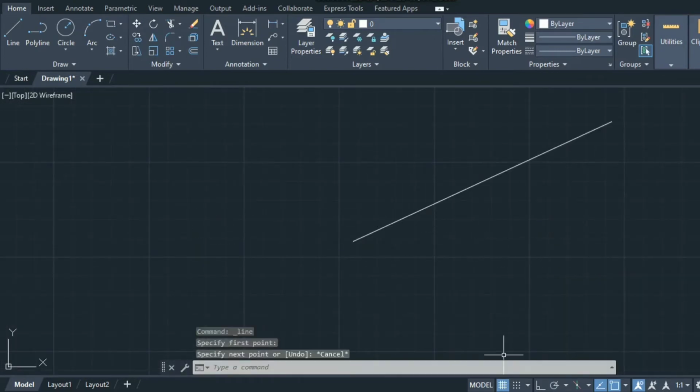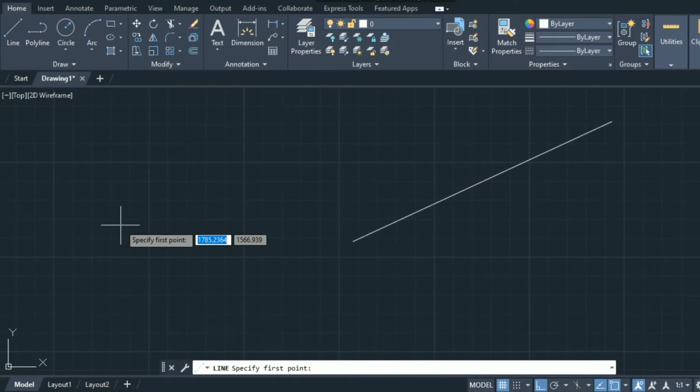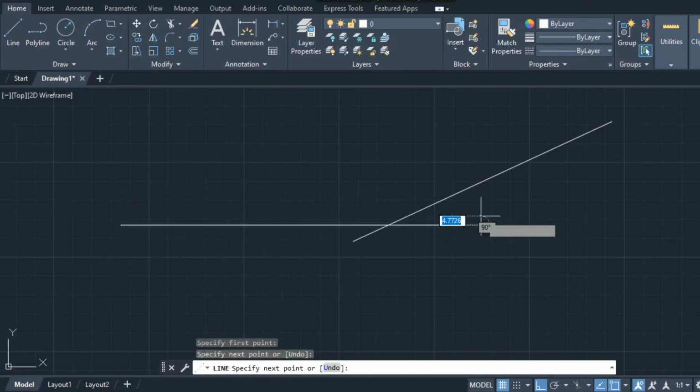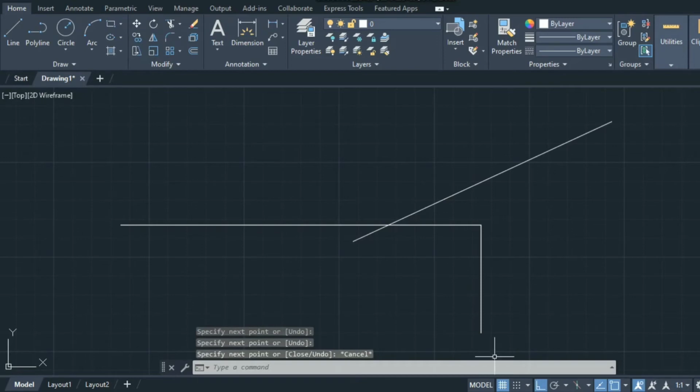In the status bar, you can see the 2 perpendicular lines here. The perpendicular symbol can be seen here. That mode is called ortho mode. This is supposed to be on, so when you click on it, it will turn on. Now you can draw a line. Whenever I click the first point and drag the mouse either to the right-hand side or vertically, the line will come either as a horizontal line or a vertical line itself. No other line can be seen over here. So with the help of ortho mode, you can draw lines either in the horizontal direction or the vertical direction.